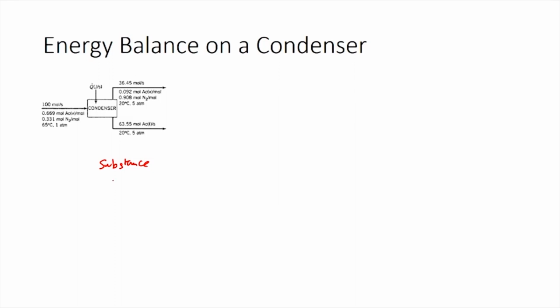So, here we will write down the phase distinct components separately. Acetone vapor will be written down as one component and acetone liquid would be written down as another component, so that we can explicitly understand and account for phase changes. Nitrogen would be another component. So, now you have molar flow rates N dot in, which is in terms of moles per second, and you